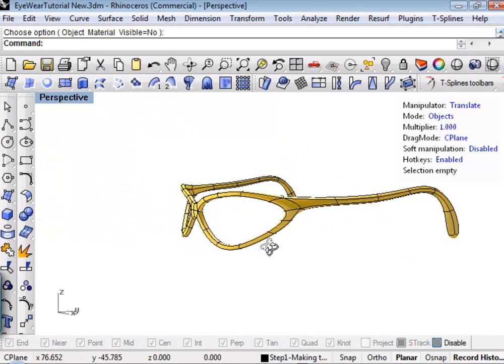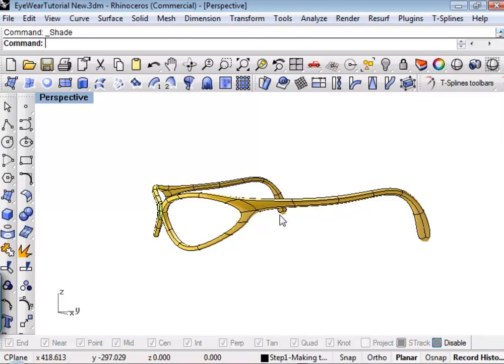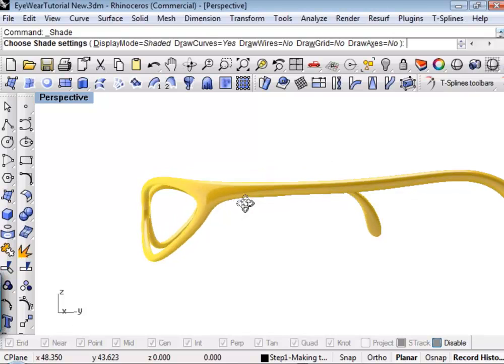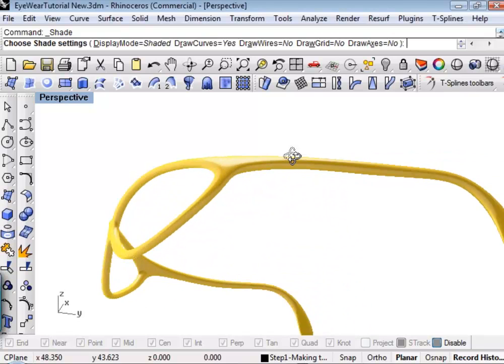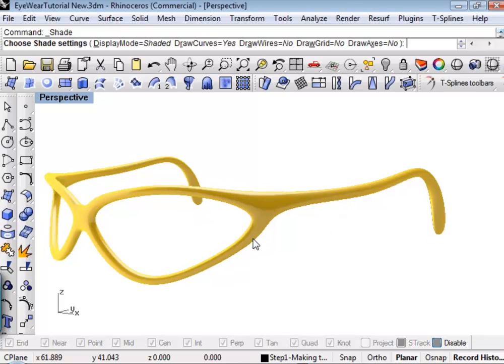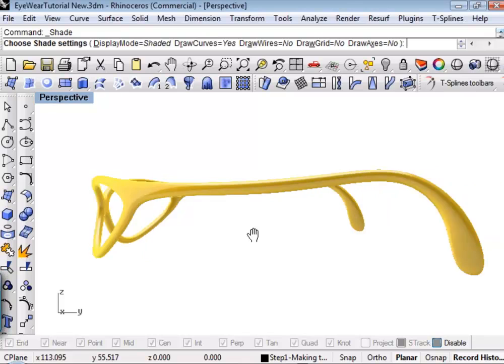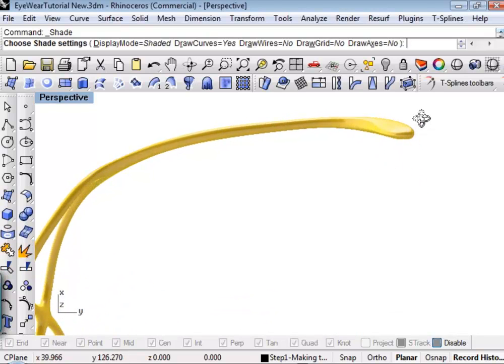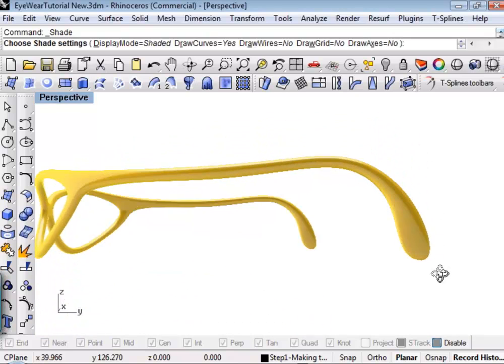So now you'll notice that we have some really beautiful stuff happening here. Stuff that's really difficult to make in NURBS. We have an organic Y branch that has a beautiful highlight running through it. We've got symmetry, so if we modify this model, it's obviously going to update either side. We've got a smooth end cap. You know, try modeling something like that in NURBS. It'll make you crazy. I know it makes me crazy. And you'll notice how beautiful that was, and we just used the tsFillHole command.